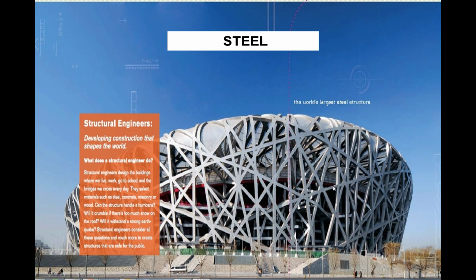So as we see, there's going to be engineering guides that tell you basically what a particular piece designation gets you in terms of length, the distance between the flanges, the length of the web, the weight of the piece per foot. So the designations basically give you a clear indication of what you need to be prepared for when you're building the structure and construction.